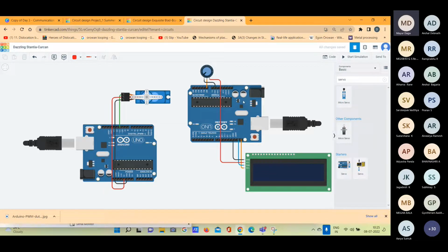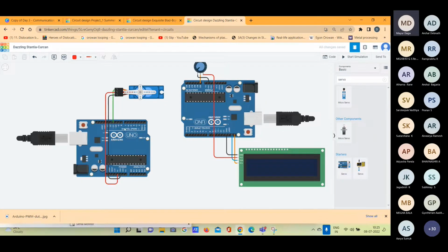This I2C LCD is a slave for this master. I'll show it in code. Now with this Arduino, this is the slave Arduino, and this is the slave I2C LCD. I'll connect it with A4, which is the SDA line, which I'll again give color blue, and the SCL clock line, which I'll give color orange as given here.